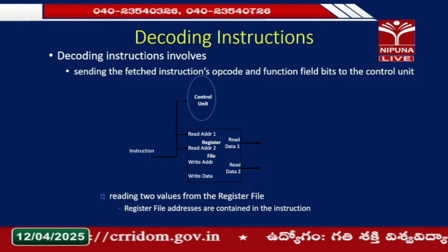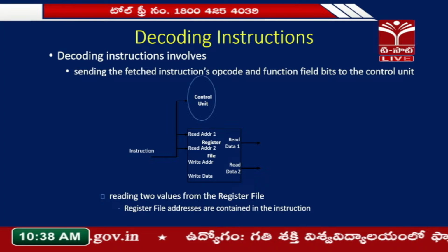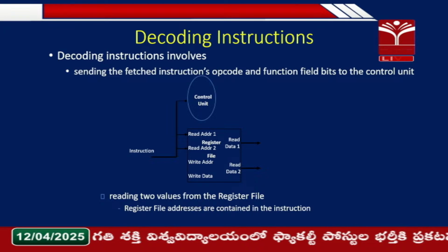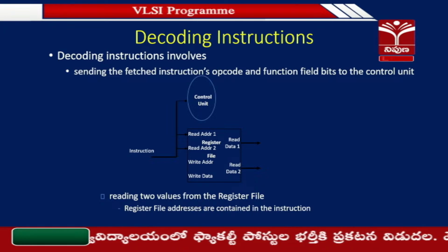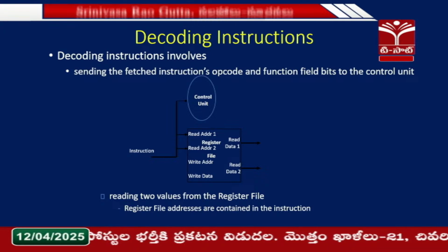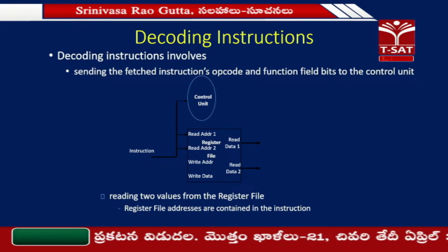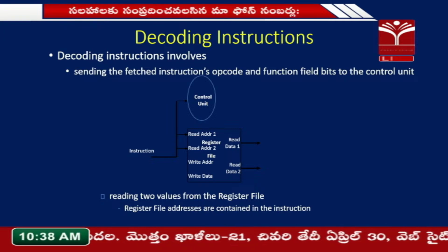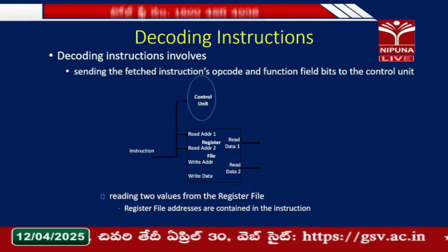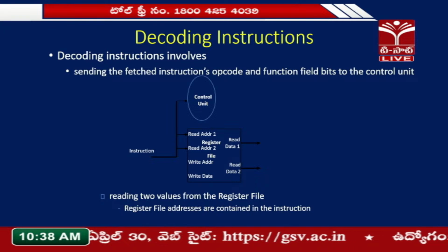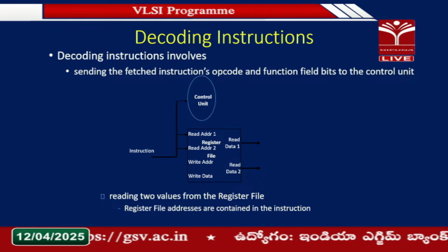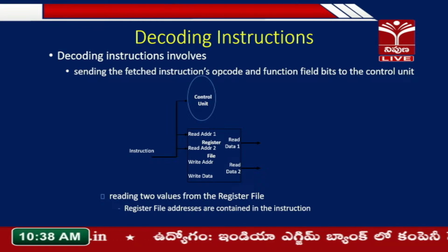Depending upon the architecture, these registers can vary from 32 registers to 64 registers. In this particular example, we have a MIPS architecture that has 32 registers. Each register has a read address and a write address, a read data and the write data. These registers can be read and written at a time, and you can see it is a multi-port kind of register file. Basically you have the 2 read addresses and a write address. It is called a 3-port register file, where I can do 2 read operations and 1 write operation into the register file in parallel.